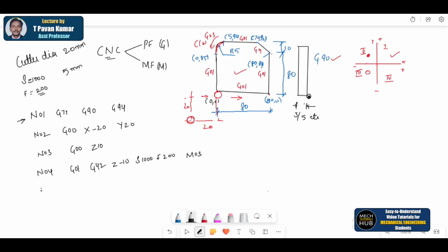Okay, then the next block, the fifth block, is nothing but G01 X0 Y0. There won't be any full stop or comma between the numerical and the alphabet X. N06 followed by G01 X and Y. X90, Y will be 0, this position, sorry, X80, Y0. So the tool till here it will travel. Okay, it will travel till that point, N06.